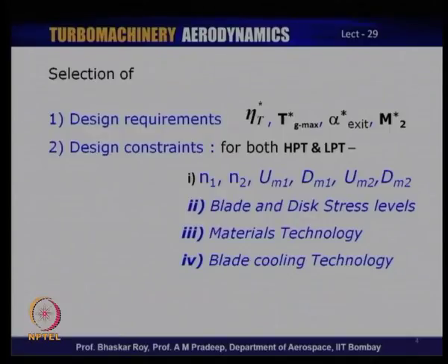One would not advocate use of this turbine at a temperature much higher than this. Maybe a few degrees higher would be all right, but substantially higher temperature would be absolutely prohibited once this design temperature has been selected and the design has been made according to this selection. So, turbine entry temperature is the highest temperature in the engine, and that is decided after a lot of technology search. And then once that is decided, at no point of time should the engine work beyond this temperature level.